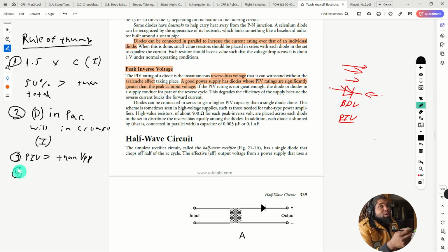But a simple way to, I wouldn't say replace a voltage regulator. The nice thing about a voltage regulator is that you usually use an adjustable voltage regulator. So you can put a trim pot, a small potentiometer, on there, and you can dial in exactly where you want that voltage to be, and it'll stay there basically forever, right? But putting diodes in series can give you a more consistent voltage. It's not regulated, right? But it'll give you more of a consistent voltage.